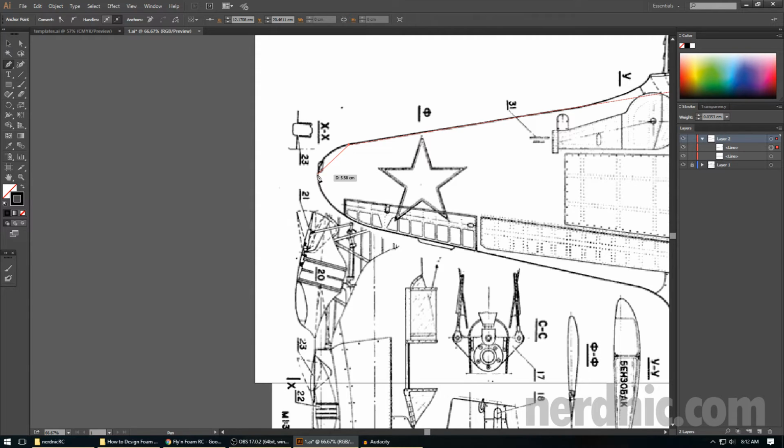And now I'm going to click and hold, so I click my mouse and hold, and now if I drag my mouse down, and the way I try to remember this is I'm going to drag it in the direction where the line would go. If you watch my mouse, if I were to be drawing the line, I would follow around the curve. I'm going to move my mouse as if I was doing that drawing, okay? And you'll see the shape starts to form. If I do the other way, it bends this way. If I do it really out, it bends out like that. If I bend it straight down, it bends as well. But essentially I'm going to follow where the immediate next part of my line is going to be.